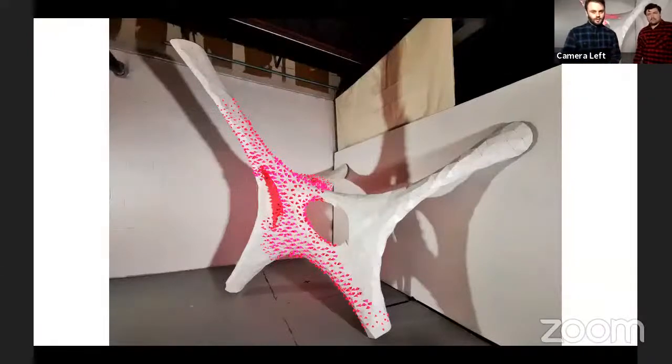Yeah, and if you look here, you see the 2 anchors on the walls are sort of floating off it. And I just want to touch back on when Jason was talking about how it allowed us that tolerance with those wall cleats. As we were building this far right arm, that was extremely important because the whole form wanted to tug to the left, and allowing it to have some leeway by sliding those anchors left and right basically made or broke this thing while we assembled it and allowed us to connect the forms that were giving us trouble and then reattach it to the wall.